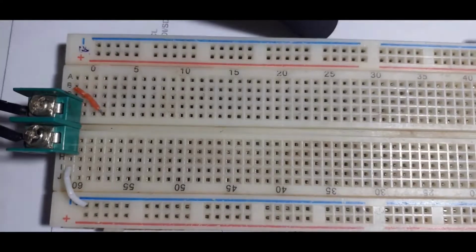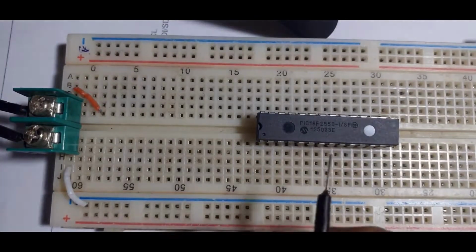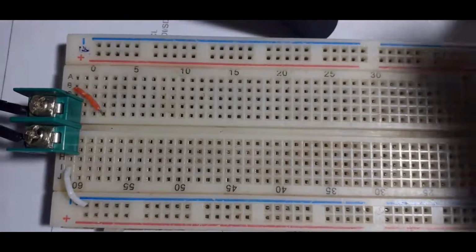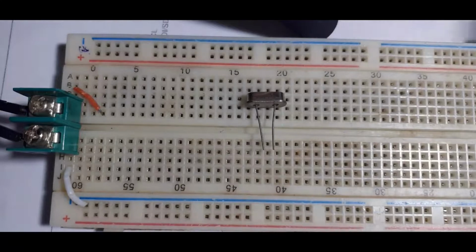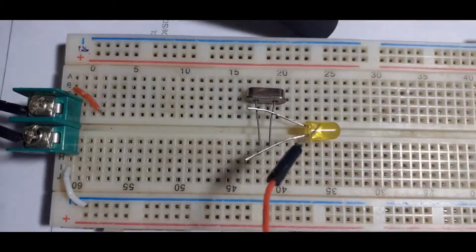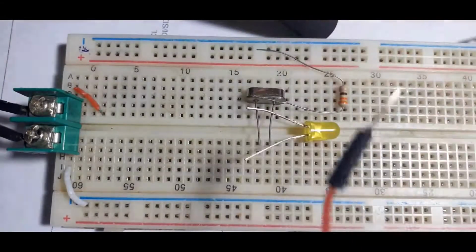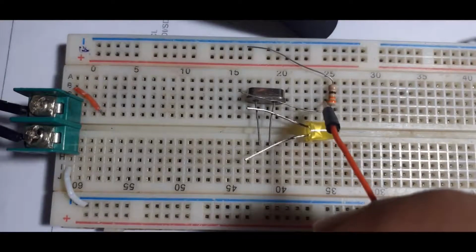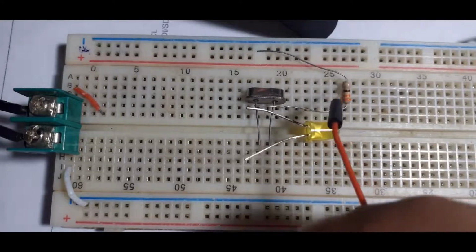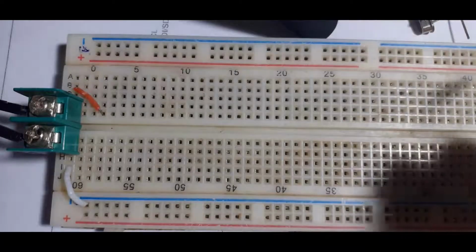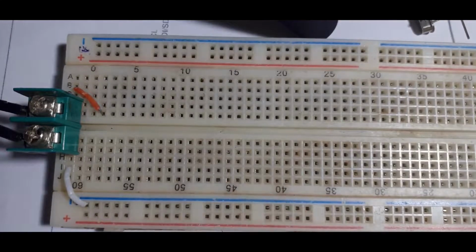So stating the obvious, this is the PIC18F2550 microcontroller, and it's a DIP package so we can mount it easily on the breadboard. Here is the 4 MHz oscillator. It has 2 pins. There is no polarity here. And the LED. Finally, a 330 ohm resistor, and since we're using it to light an LED, don't get frustrated if you don't have this value. Even a 1K ohm resistor will be fine. So let's see how we can put all these components together to get the circuit working.